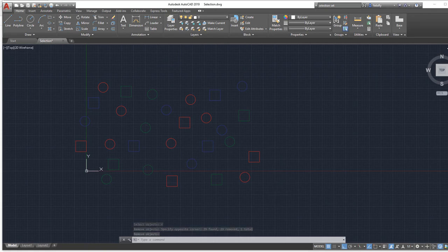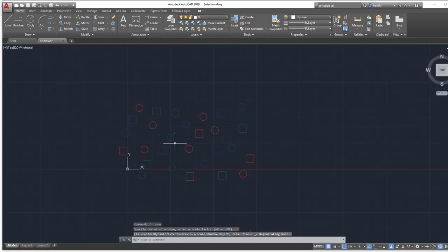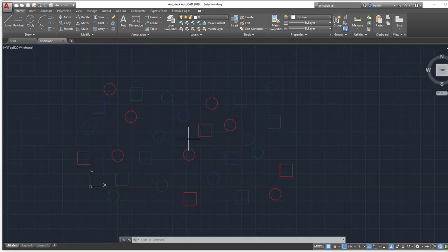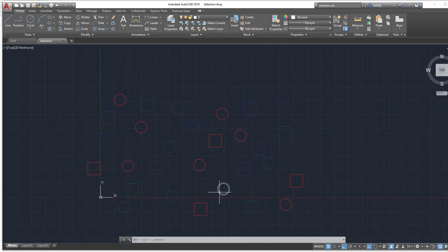And then if you zoom extents, what we've done there is we've selected all, and it's picked automatically all these random objects all over the place. We haven't had to zoom around and find all these little full stops and bits of lines and bits of hatching. It's selected all, everything in the drawing. We've deselected what we want to keep and erase. So that is the main reason I use select all. But it does come in handy for other things as well.